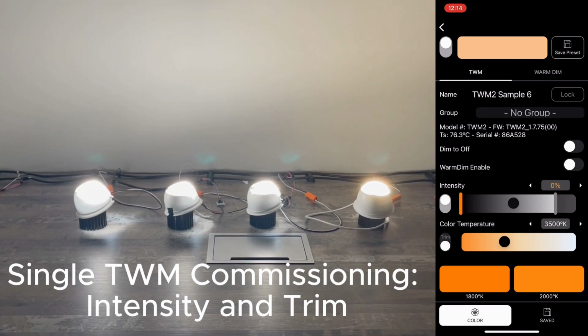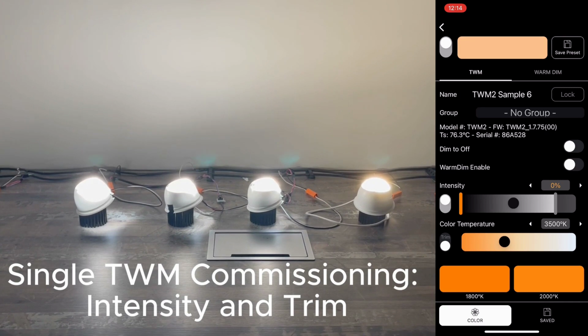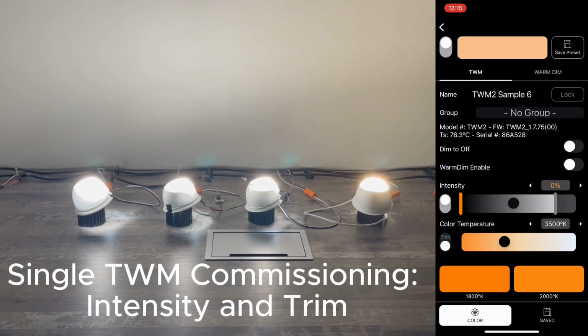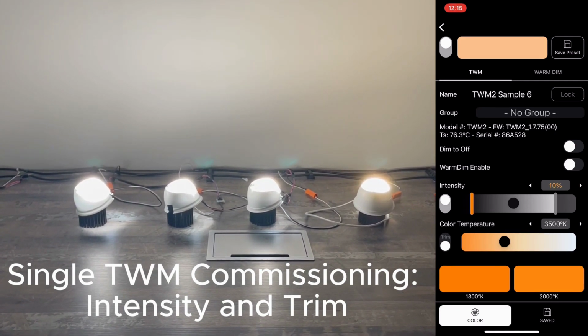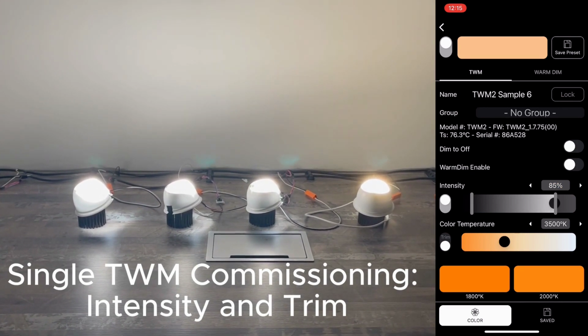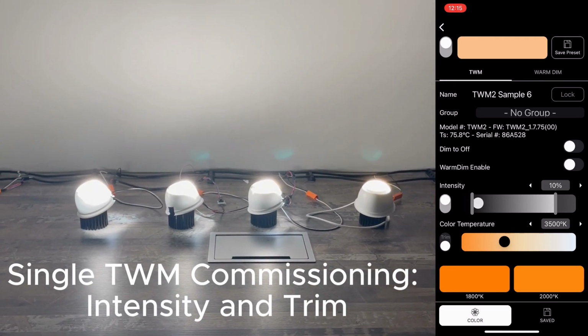For the minimum trim, or the minimum dimming percent that you like, you can change it from anywhere to a good amount. For example, let's use 10% here. So now we've set 85% as the maximum intensity for this unit, and we can also use 10% as the minimum intensity for this unit.